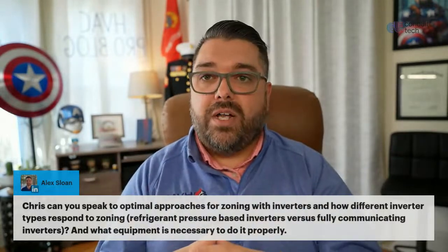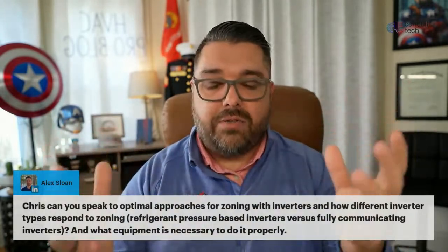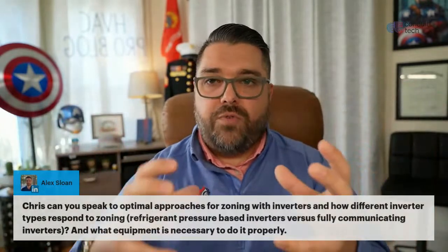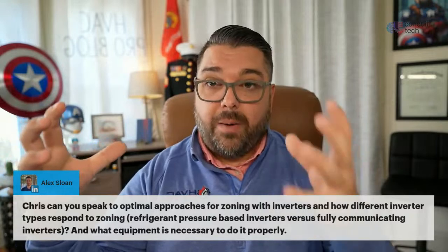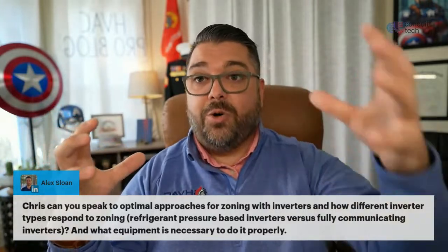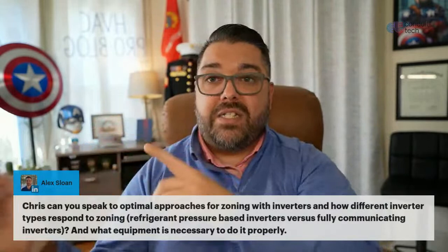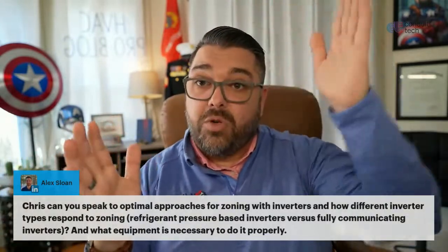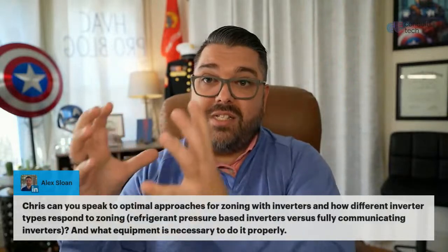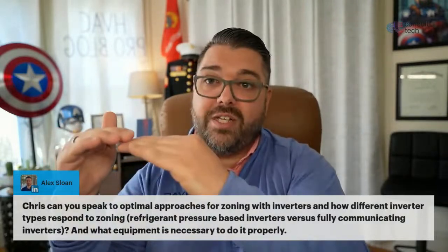So as an example, and I'm just going to pull a manufacturer out of the hat here, like Bryant, let's say. If you're using a Bryant variable speed furnace and air conditioner, you want to try to get a Bryant zoning system that's going to work and communicate with that, because when one or two dampers, however many dampers turn on, it communicates to the furnace to say, this is what we should run at. And then the furnace runs at that.